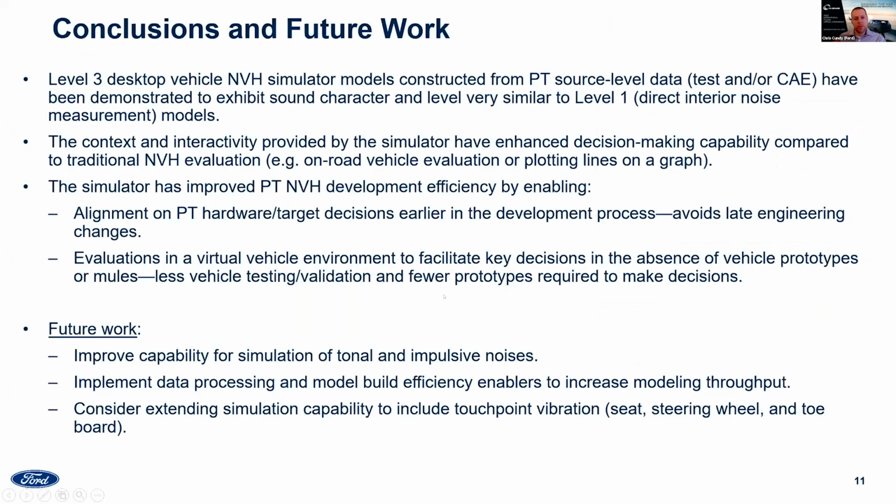So in conclusion, we've shown that level 3 simulator models that we construct starting from the powertrain source level data, combining that with transfer functions to get contributions, exhibits very realistic sound character. It's accurate, similar to direct interior noise measurements. So we have confidence in using this approach to make decisions.